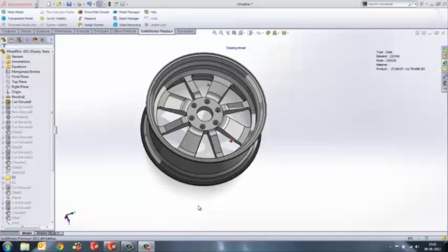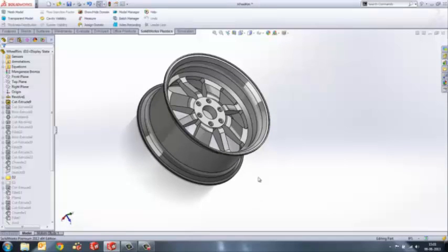Based on that input, we as designers verified that we can apply nylon material, Ultramid nylon from BASF, so that it can replace this manganese bronze alloy. So how are we going to do that? If we make the rim out of plastics, that is nylon material, how is it going to be manufactured? We can produce it by injection molding technology.